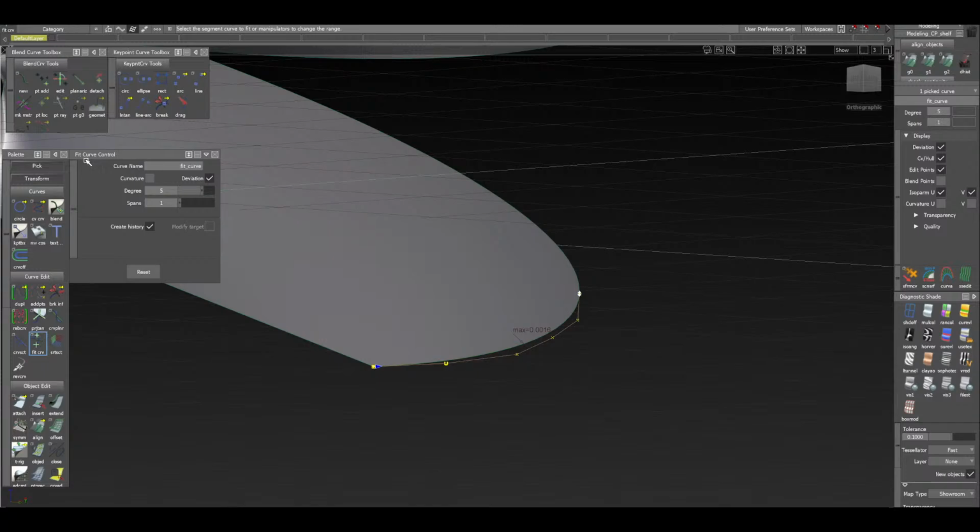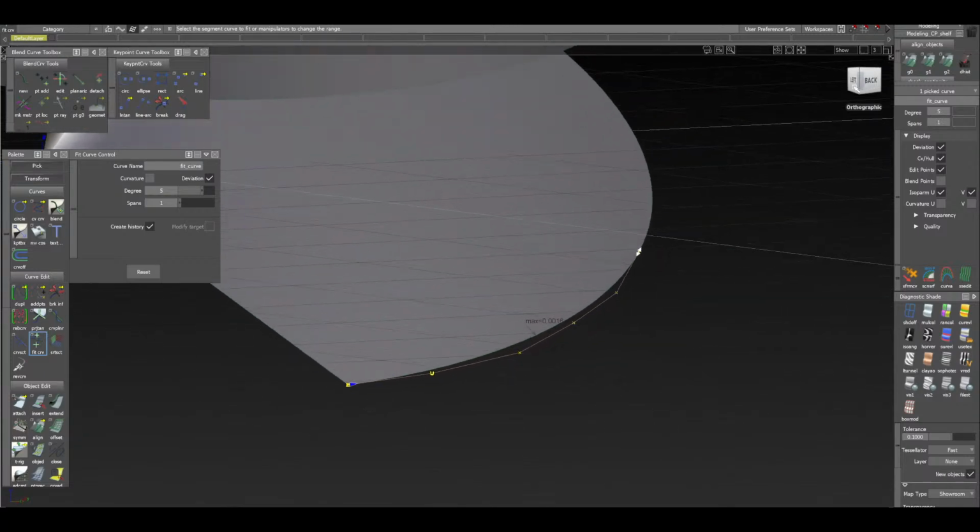Why have I decided to match a fit curve to the edge of the surface? Why did I decide to do that? I decided to do that because if I'm creating a tube or a pipe or a section of a pipe, I need to create an axis, and that's actually what I'm doing now. I'm setting up the software so that the tubular offset tool, once I've established everything else, is going to be able to identify an axis, and it's going to be able to build off of that information.